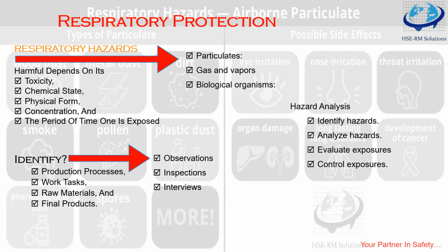Analyze: use safety data sheets, SDS or MSDS, material safety data sheets, and other data to understand the nature of exposure. Evaluate the exposure to determine whether the exposures are higher than the safe levels. And finally, control exposure by using the evaluation information to reduce exposure to the safe level.